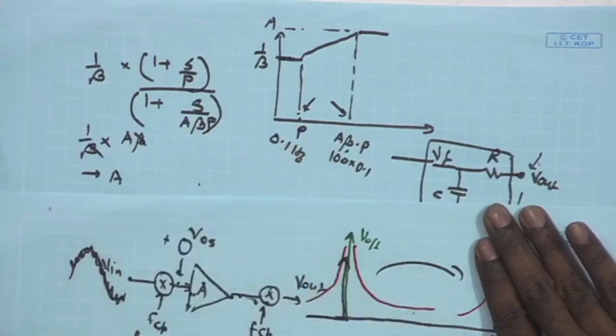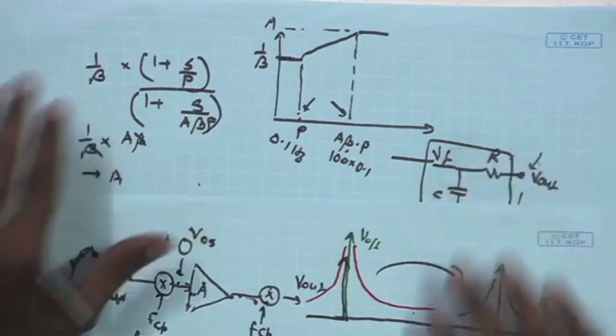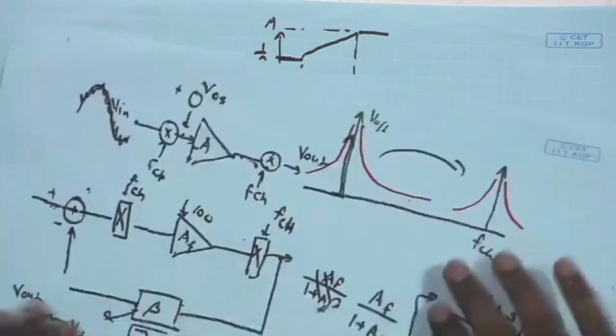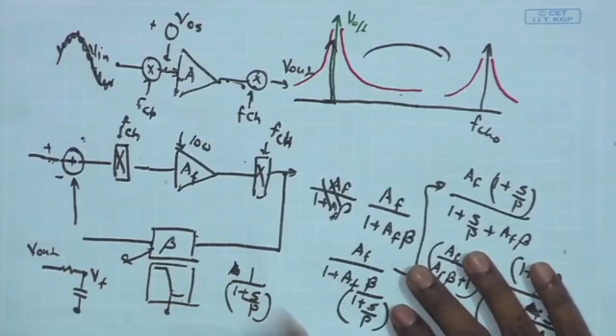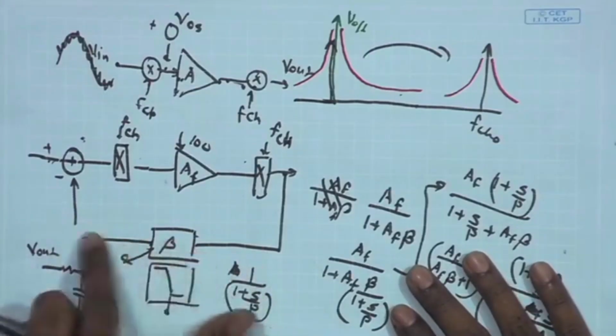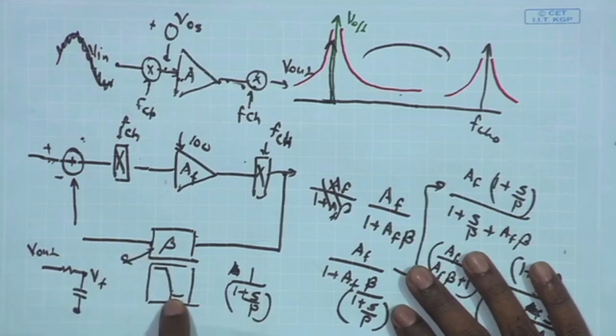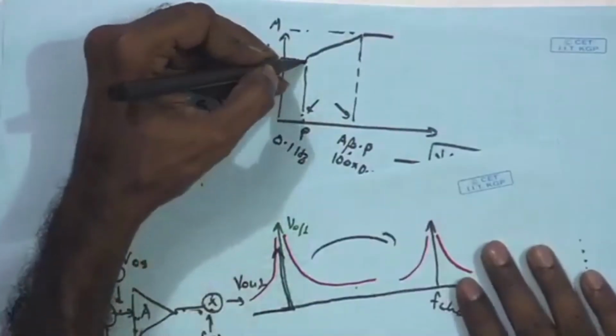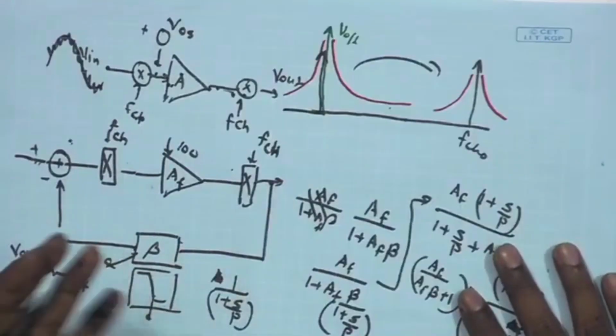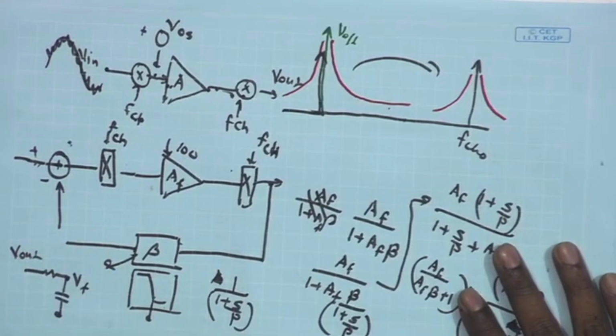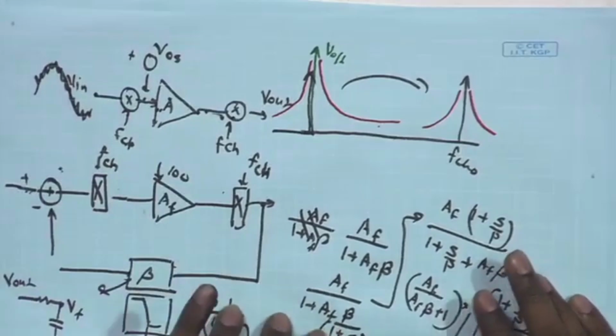That becomes challenging, and for that we need to make sure that the transfer function in the feedback path is such that it is able to suppress, or provide a steeper roll off. So, rather than having a single pole response, I can have a steeper response over here, a 2 pole response, and in that case this curve can rise steeper. So, rather than putting just a passive RC filter over here, I would like to put some active filter or higher order filter, so that the steepness of this transfer function can be much stronger. That is what we need to look into.